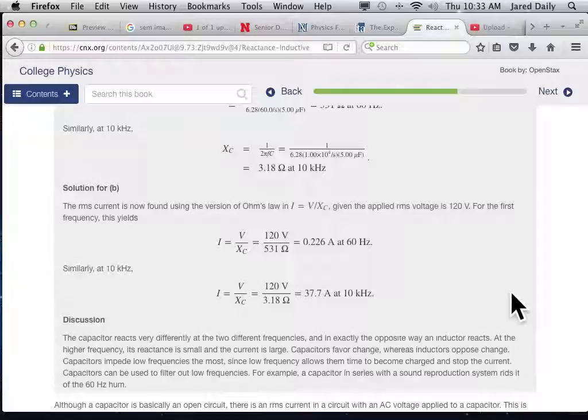What if we use these together? Something that cuts off things at low frequencies, something that cuts off things at higher frequencies. We could narrow an area of frequencies that we let through if we use them together. And that's exactly what's used in your phone. Your phone has a variable capacitor and a variable inductor that can change. You can change those two things so that you can shift around which frequency you're going to let through.